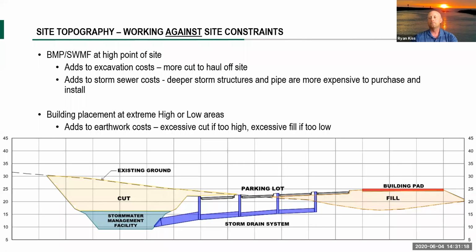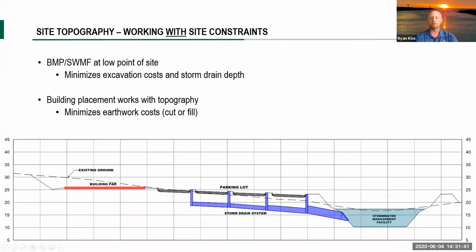and fill. And even if you are balancing a site and balancing between them, this dirt still needs to be excavated and still needs to be moved. So even though you may not be importing or exporting a lot of dirt from the site, you're still moving a lot of dirt around on the site, and there's still a price tag and a cost associated with that from the contractor as well. So just keep that in mind, that doesn't just make your dirt problem go away if you say that you're going to balance your cut and fill. You still are driving construction costs in doing so.